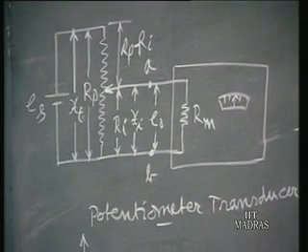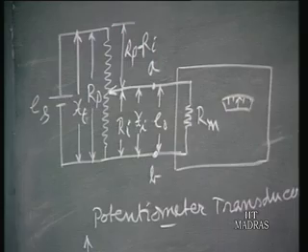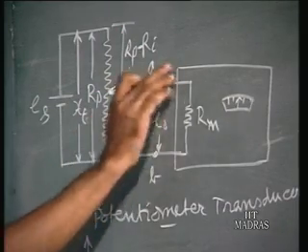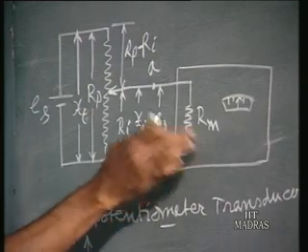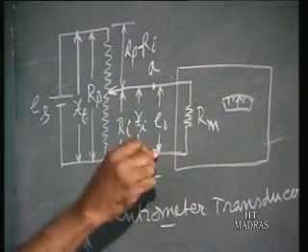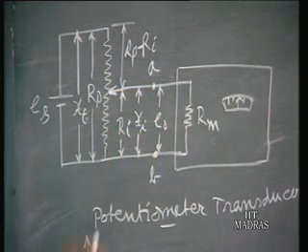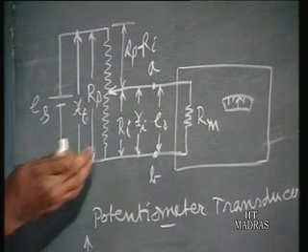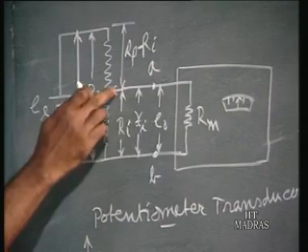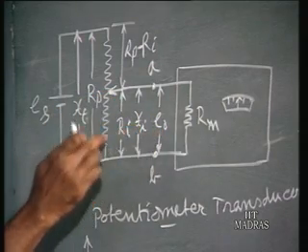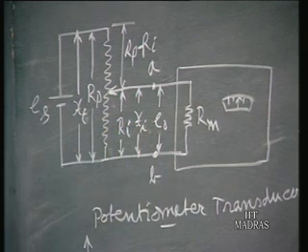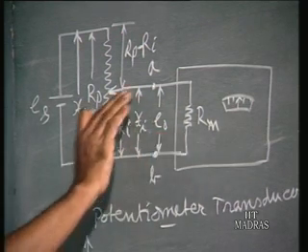That is, now we are connecting an instrument Rm. In case it is open circuit, A and B are open, no meter is connected, it's a voltmeter. If you don't connect this voltmeter, it's an open circuit voltage Eo. So Eo dash, open circuit voltage, will be proportional to Xi. If Xi is 0, you have 0 voltage, and at the end of the travel, the total voltage would appear here, and so on, proportionate. But once we connect a voltmeter, you find the loading effect.